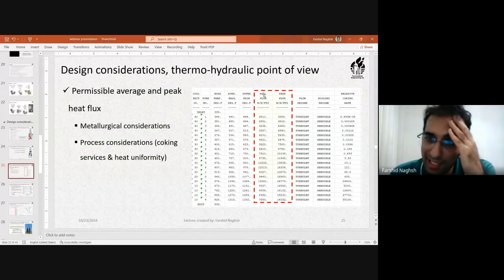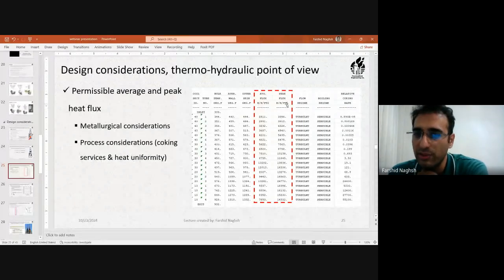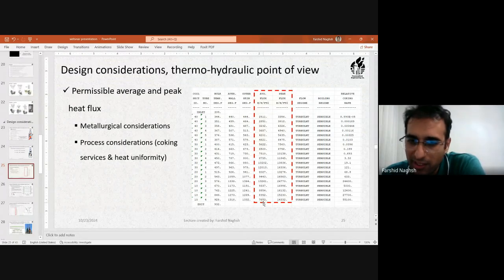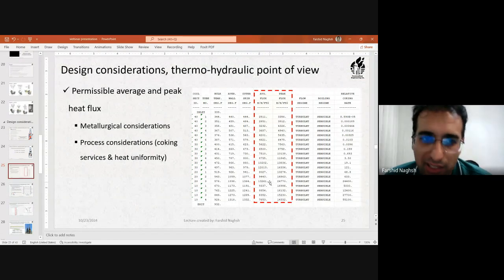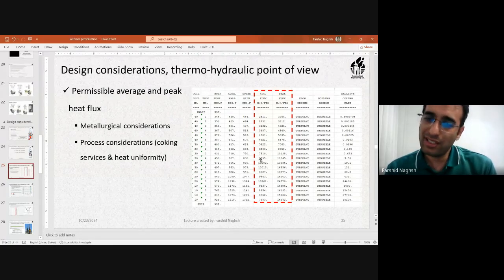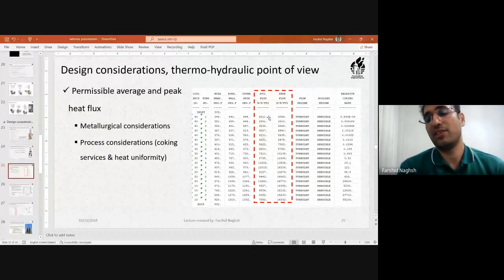You see that the unit is BTU per hour per square foot. You see that flux, this is the radiant section, and up above we go to the convection section. You see that I have kept the average flux something around 7,000, 8,000. This 13,000 is a little bit high. The limitation for this process is 12,000 based on the data sheets or project specifications by the client. So they are mostly uniform, and the flux is very, very well distributed.